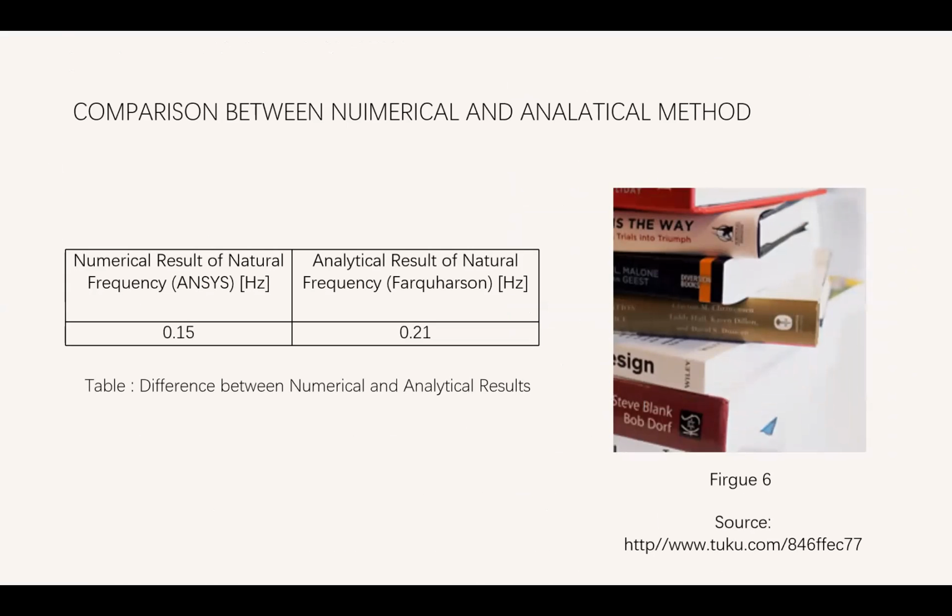Analytically, the determination of the natural vibration frequency of a real-world suspension bridge has been regarded as very complex work. Instead of using the analytical method, a numerical method such as FEM was considered a higher efficiency approach to estimate the natural vibration frequency than the traditional analytical method, like I just talked about before.